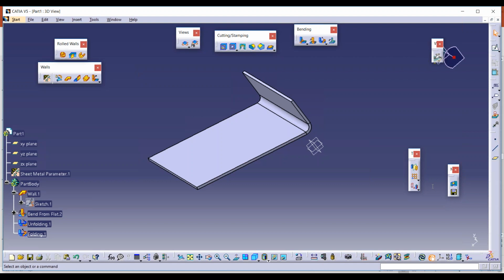Okay, sir. For example, if we take the common rail for vehicle assembly, how do they create that bend for sheet metal? They'll create it in a part and bring it back into the sheet metal. I didn't get you, sir. They will create those kinds of structures in part modeling and then bring them back into the sheet metal. They'll not create it in sheet metal itself.